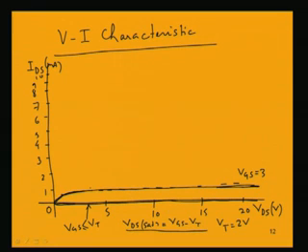As VGS minus VT gives the locus of the point of this VDS, for VGS equal to 3 we are considering VT equal to 2, so it will be 1 volt. So, somewhere here say, we will be having basically a locus like this. That will give you this relationship of VDS saturation equals VGS minus V threshold. So, for a particular VGS, the saturation value of VDS is this much.